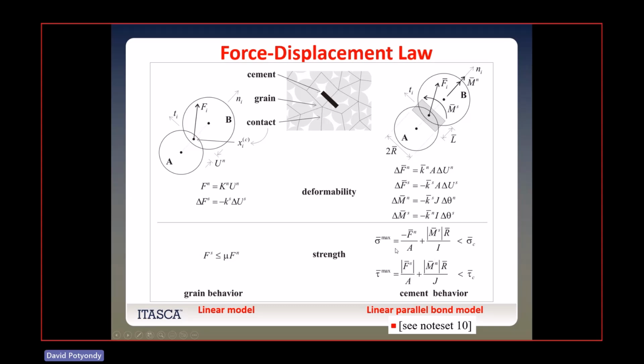What we do is we think it's a beam of circular cross section, and we compute the maximum outer fiber stress that's stretching. So if you bend a beam with moment applied, you're going to get an outer fiber stress, and that's actually going to be M times y, distance to the outside, over I. That's what you're seeing here. This is the bending moment times y, this is the distance to the outer surface.